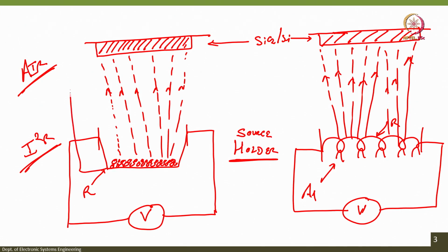That collision will cause distraction, and because of that the material that is melted may not reach the substrate uniformly. So, what is an alternative? The alternative is that we make sure that the material can travel as much as possible without colliding with any other particles. That means, the material that we want to deposit, when it is melted and evaporated, can travel the maximum distance before it collides with anything. If it does not collide, then we can get a better uniform material layer or thin film on the substrate. So, to do that, what is a solution? You have a vacuum.